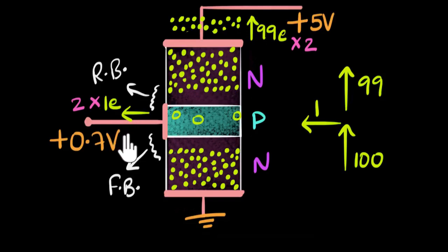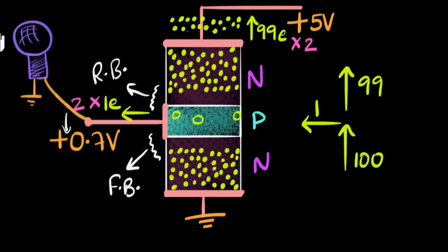exactly what we needed. And so if you want to use this to amplify your sound, then you can connect your microphone wire over here. Now, the microphone will be the one that will provide the voltage over here needed to forward bias this junction. And the voltage provided by the microphone will depend upon the sound. If your sound is very loud, this voltage will be high. If the sound is very low, like you're whispering, the voltage will be very low over here.